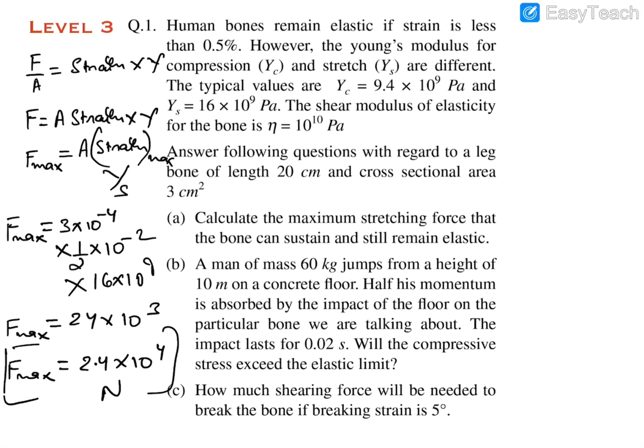newtons. Now, in the second case, it is given that a man of mass 60 kg jumps from a height of 10 meter on a concrete floor, and half of his momentum is absorbed by the impact of the floor on the particular bone. So the impact lasts for 0.02 seconds. So we have to verify whether this compressive stress will exceed the elastic limit or not.